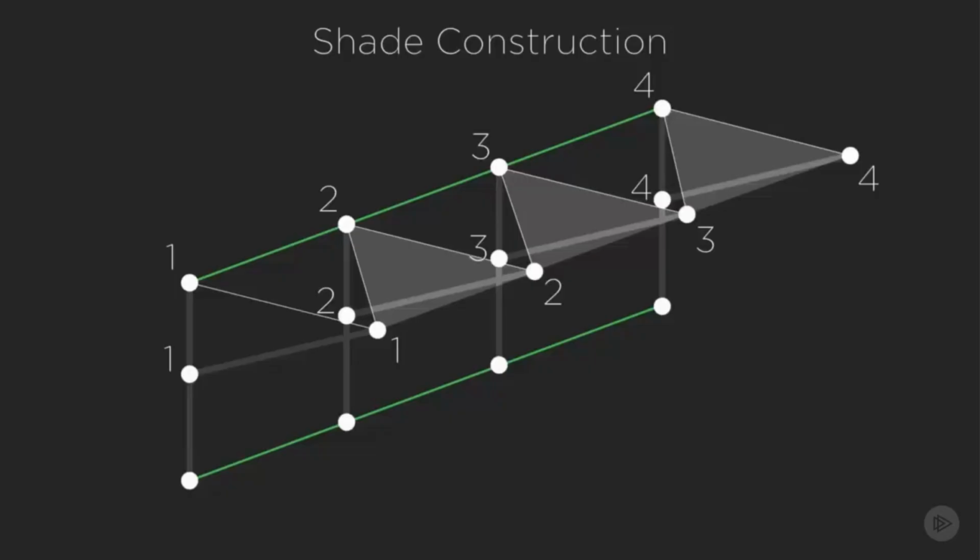In this case, I'm going to move the point of connection for each of my panels along the z-axis, the world z-axis, which means it's just going to go straight up and down. And then I will plug that point into the list create for the 3-point adaptive component panels inputs.